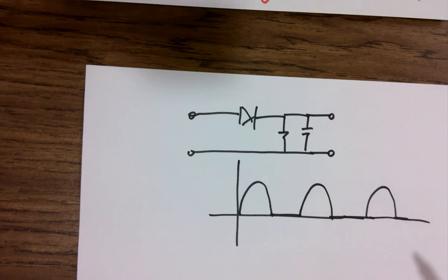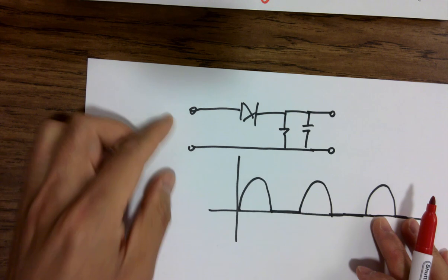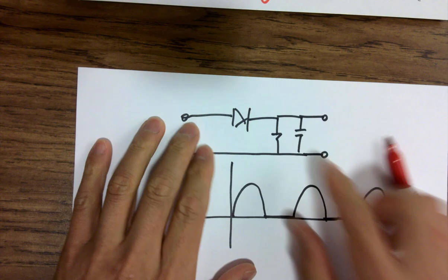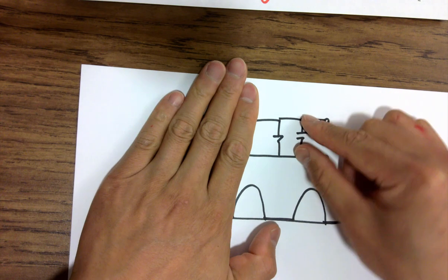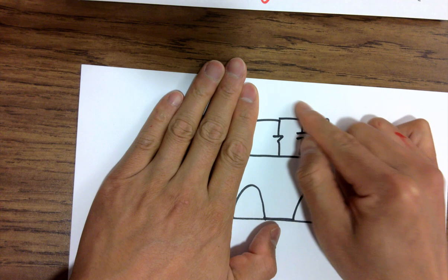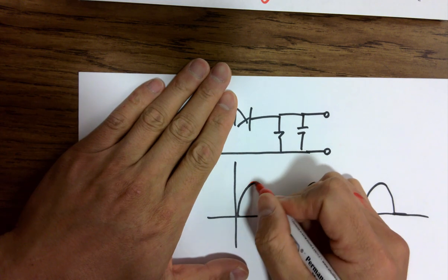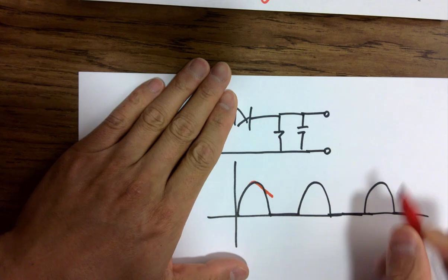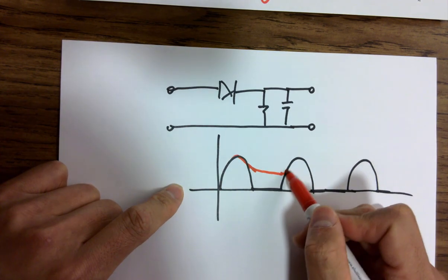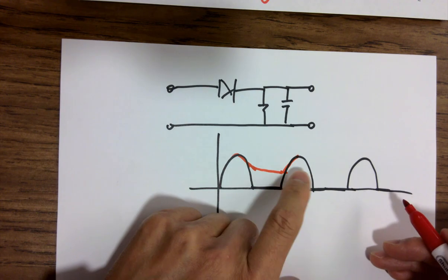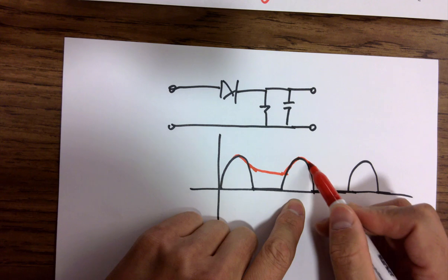It slowly decreases. Why? It's discharging through the resistor. It's charging up the cap, and whenever it goes to 0 volts, when nothing can go through, this one starts discharging through the resistor. So it's going to charge up and discharge to a certain point, and then go back up whenever you get a cycle going up again, right? So you're going to do this.